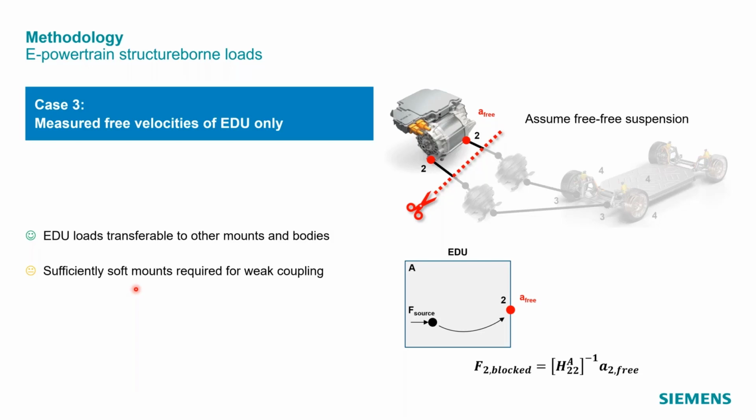In practice, and what I will show in the case study, is that for very heavy components like an electric drive unit, this tends to be okay. So for this specific application, powertrains in general, you might say, because of the softness of those mounts, this free acceleration method tends to give you the best of both worlds in a very usable frequency range.